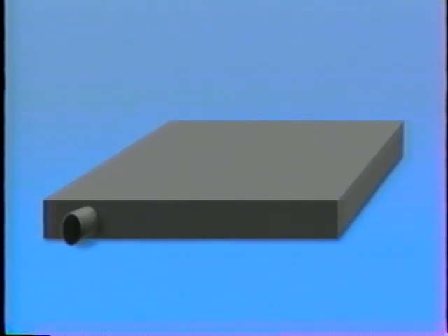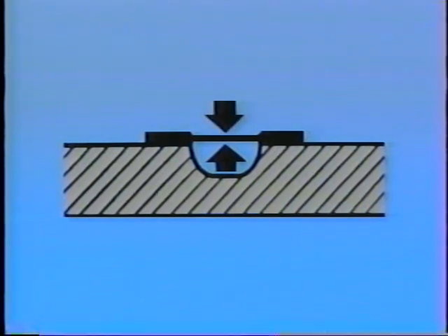through a small tube. If you look at a cross-section view of the glass and the silicon chip, you can see that the air trapped beneath the chip exerts pressure from below, and air piped in from the manifold exerts pressure from above. When the chip is first sealed to the glass, air pressure is controlled to exactly 1 atmosphere, which is equal to 14.7 psi, or roughly 30 inches of mercury.